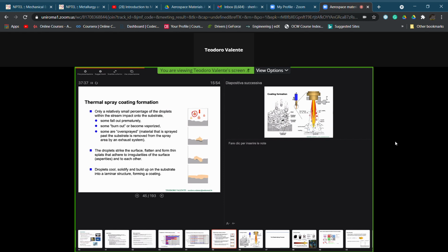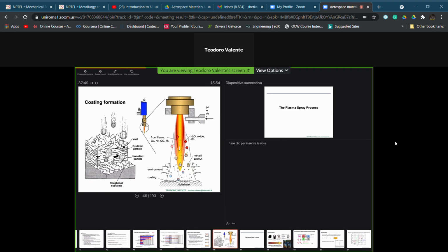And why do we have the lower value, about 100 micrometers? Because you have a single powder splatting, okay? Let me discuss this on this slide. You have the single splat, which is this one. Then you have another splat, which is this one. Well, more or less, just to give you an idea, when you have the liquid powders and they splat, the height after the impact is something around 1/5 of the original diameter, okay?